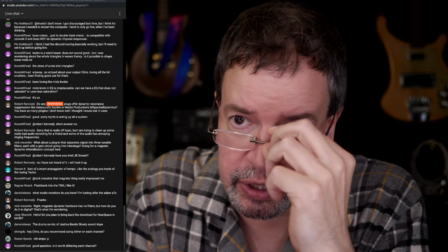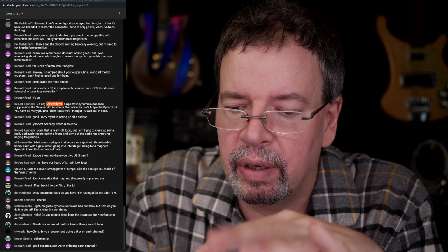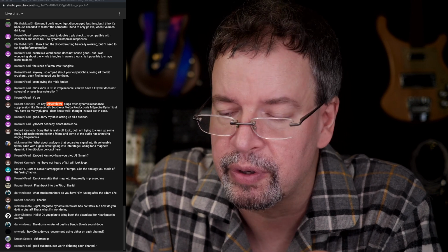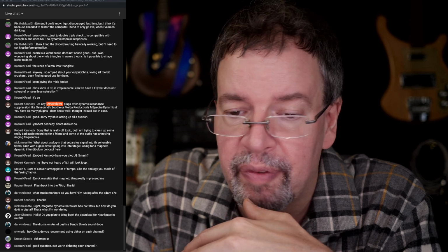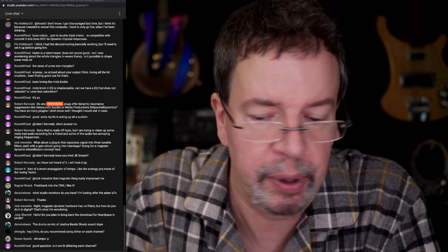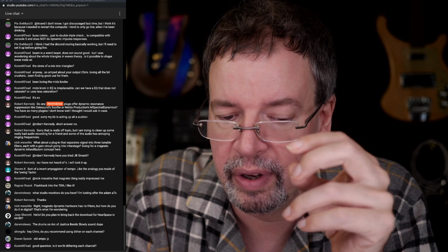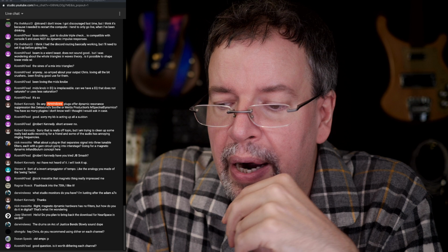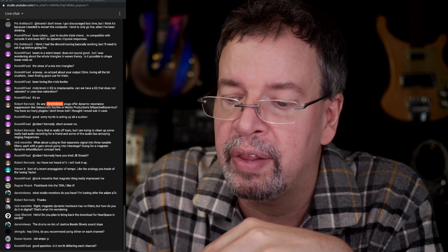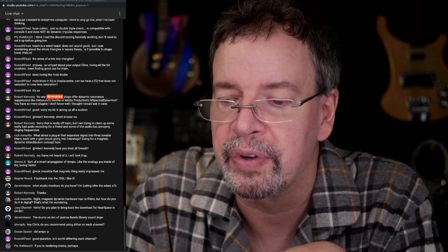you've got your near reflections, right? So you've got close-up things, and your near echoes and stuff will produce a bunch of comb filtering and things like that. You've got far-field echoes where you can run through all-pass filters, have that sort of bloom effect. I have MV that does that. MV gives you purely bloom effect, purely stacked all-passes. And that does a pretty good job of deep field stuff. And in my experience, we've always gone for doing the near field echoes, and then, because it's a logical thing, fed that to the far field stuff.